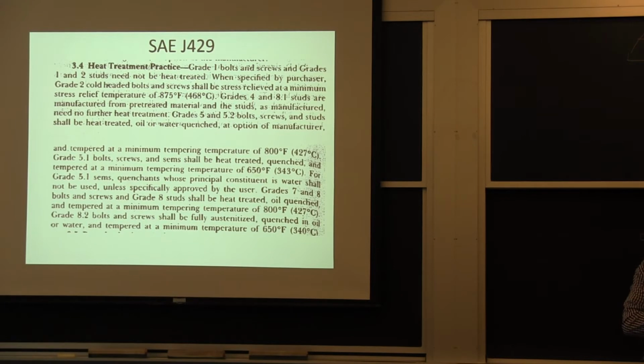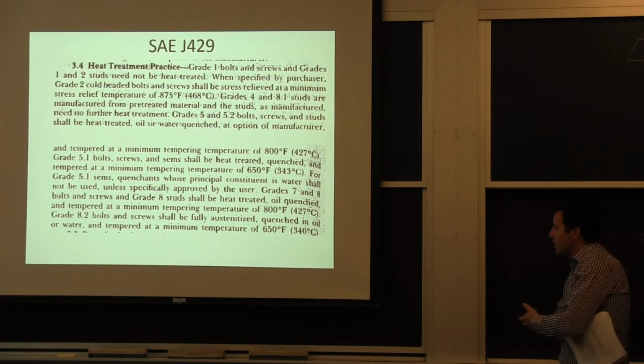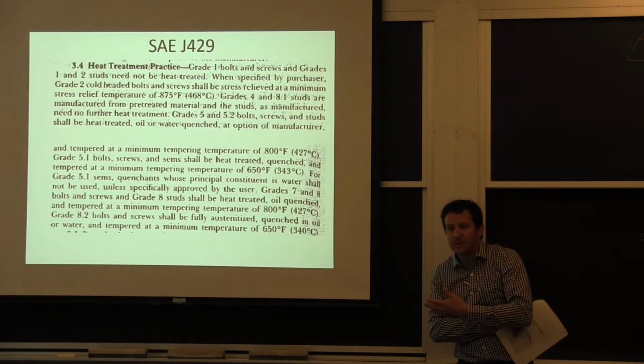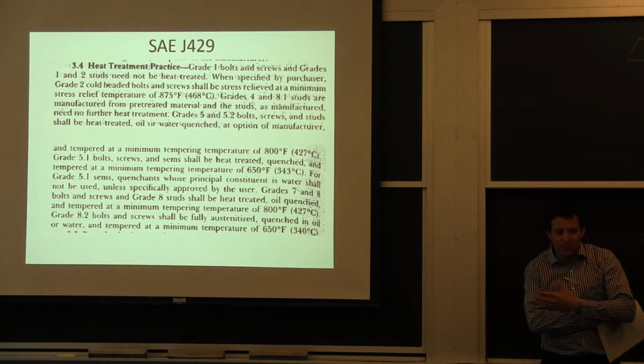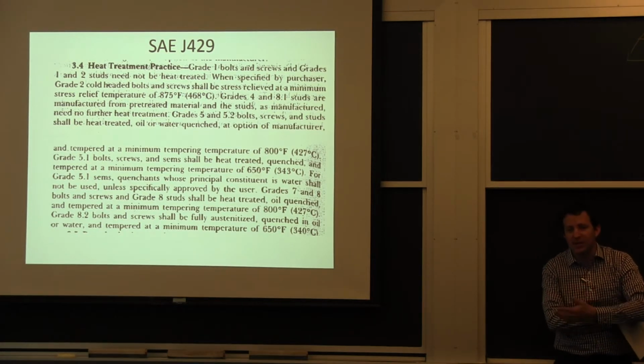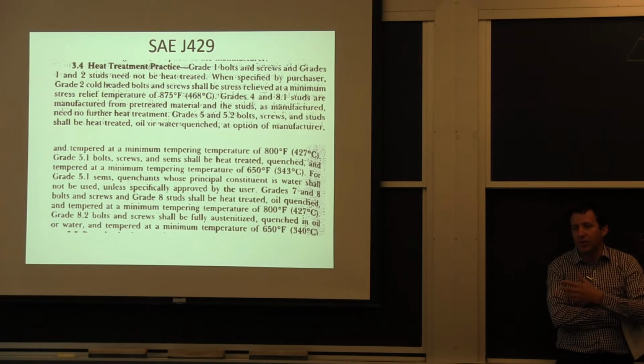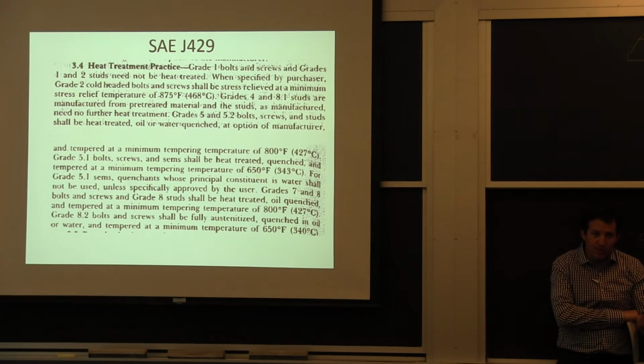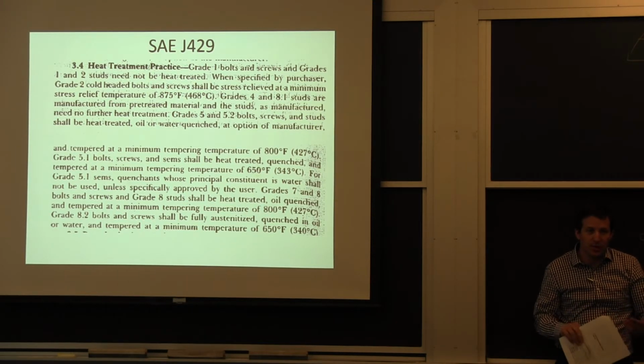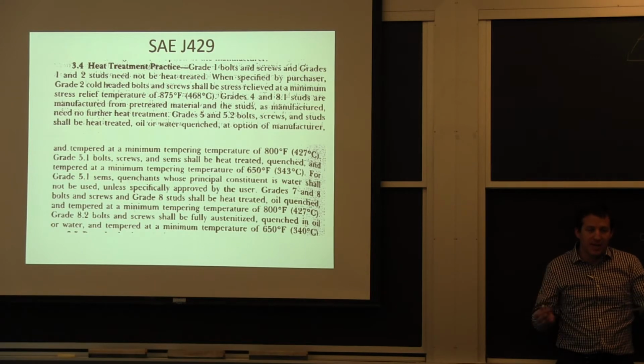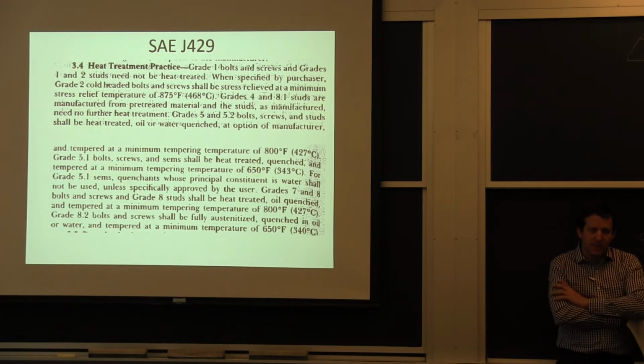One of the reasons is you get the best in terms of your surface properties. And one of the consequences is that every once in a while someone will buy a bar that's been quenched and tempered to the same requirement and machine threads on it, and you don't get the same properties than if you did it the other way around, getting to shape and then doing the heat treatment.